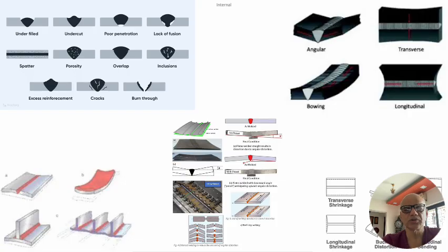While welding also, through the screen you can see the sparks which are getting generated and the droplets of weld getting deposited onto the side of the weld on our jobs which are getting welded. And then this also becomes an activity to clean. These could sometimes be big ones which may have a good fusion, so you have to grind and remove them, and these are not good aesthetically, as well as in sensitive alloys like alloy steels. These could be stress risers in case they happen to be the big ones.